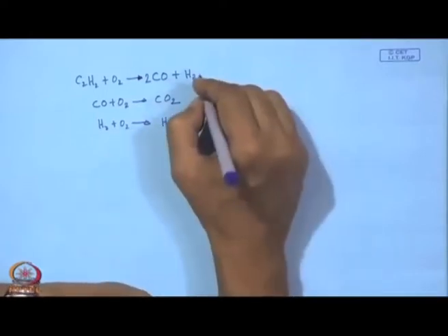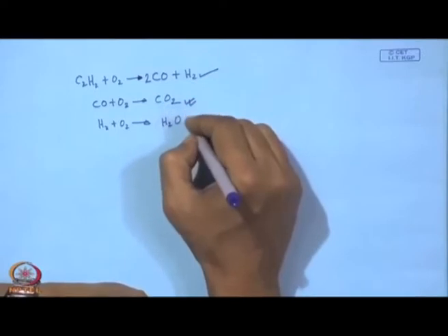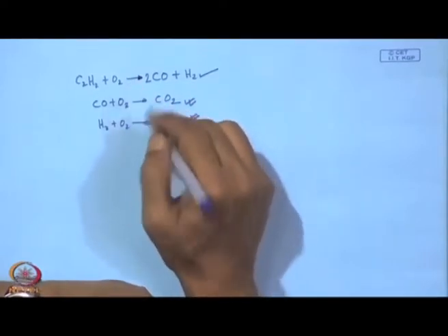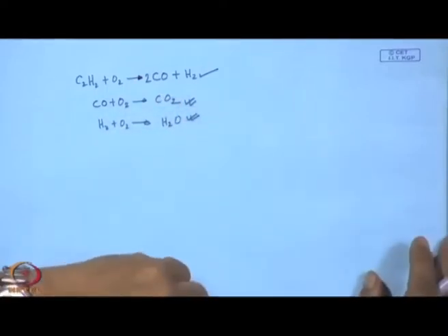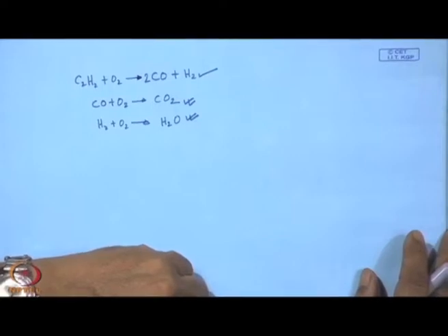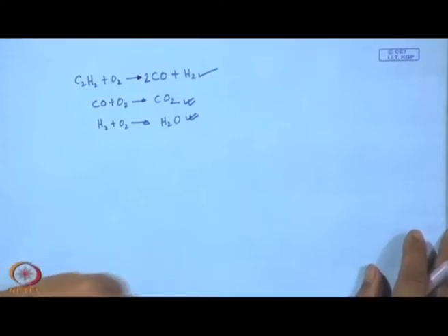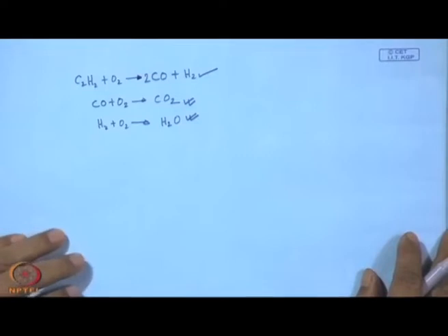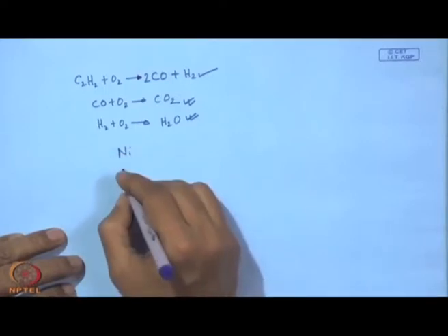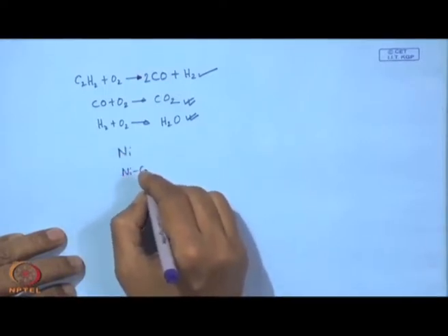So, this is the first stage, and these are the second stage of the reaction, and through this reaction a huge amount of heat is available, which is an exothermic reaction, and the available temperature can go as high as 3000 degrees, and that should be sufficient for these materials, which are basically nickel base alloy or nickel chromium alloy.